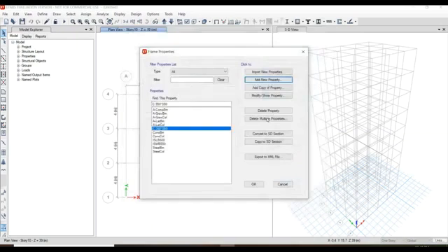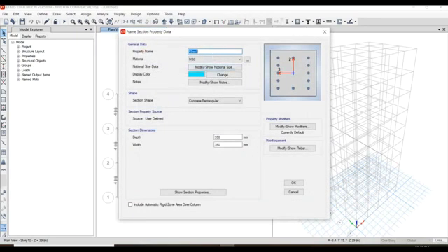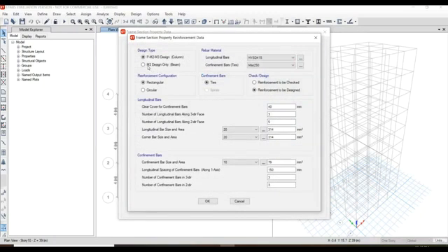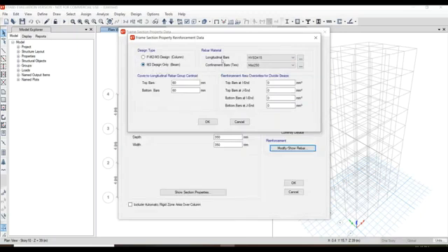Click OK and OK. And also click on the column 350 by 350 just created and add a copy of the property, so that for easy purpose we can add a beam of 350 by 350. Or else we can change to any other name as we wish. Take M30 in the drop-down, and depth and width are 350 and 350 as we did the copy of the property, and modify the rebars. Check M3 design only, because beams should be designed for only moment M3. These are for beams, and the longitudinal bars are HYSD 415 and the stirrups are mild 250.